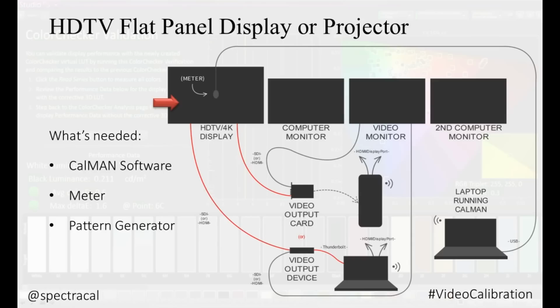In either system configuration, the laptop or desktop, for the first pass, you'll want to optimize the internal controls of the flat panel or the client viewing monitor, and this typically involves setting things like brightness, contrast, color temp, color space, aspect ratio, and then balancing the white point with RGB controls.